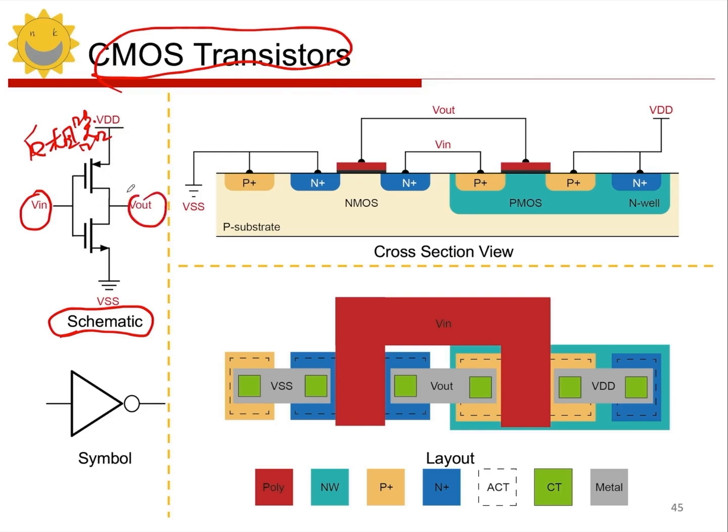Here's its schematic, and there's also something called a symbol. Later on, we'll talk about how, if you can use EDA tools to design this schematic and layout, there will be several views. Our schematic is usually presented in a schematic form, and this schematic will have a corresponding symbol. This means that when we call this schematic, we don't have to display the specific structure every time. Instead, this specific structure will have a symbol to represent it, and that symbol is the one for the inverter, right?